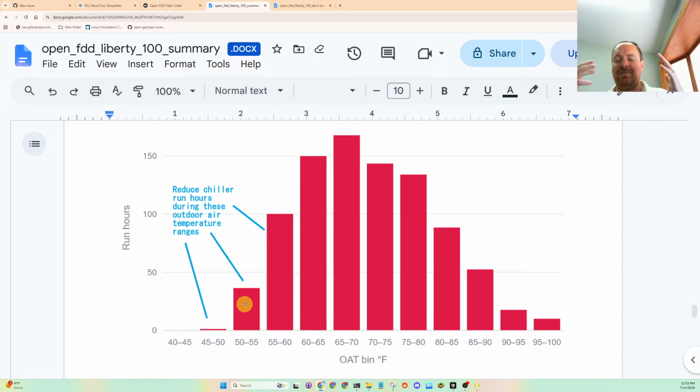And yeah, we need that visualization that these dampers fully close and they fully open and there are good seals. A lot of the time some of this equipment is so old that there are rubber seals, gaskets on the blades of the economizers, and sometimes those are gone. In really old air handling units, I've seen in the mixing chamber a pile of rubber gaskets that have just fallen off the blades, and pretty soon it's just economizer blades.